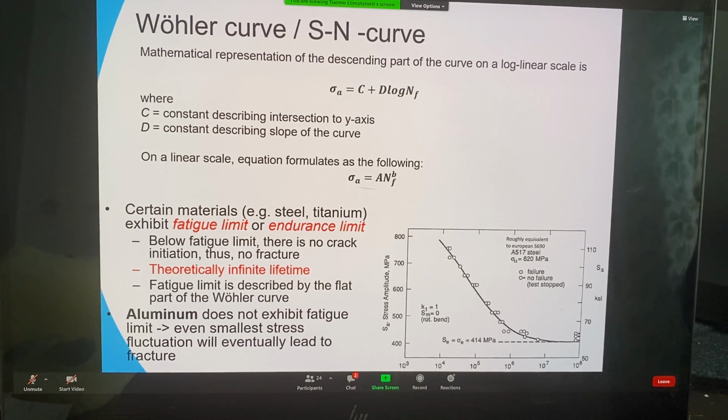Yes, of course. For example, if we design the spring, like in this picture, in a way that the loading would be below 400, that would give us more or less infinite lifetime. Now, if we at some point increase the loading, the driver is driving too fast on the bumps, and the spring is then in the range of 500, that would of course mean that the spring has then a defined lifetime, which we can find from the Wöhler curve over here.